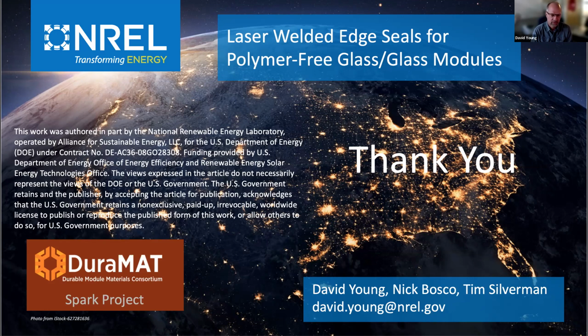But that's certainly one of the next steps, to see if tempering is going to be a problem. One of the workarounds might be to use the laser to detemper in that local region and then perform the weld. So basically release the stress in a thermal way right before you complete the weld. But it's definitely an open question.